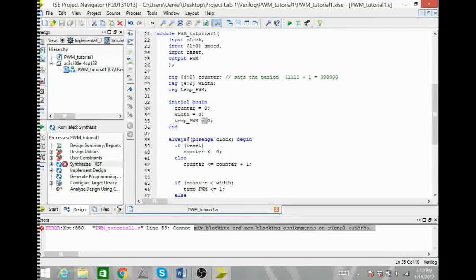So this one would be a blocking. In blocking, it creates a sequential mode where the next line will not be allowed to happen until this first line completes. So that's what the term blocking is called. So it blocks the next line from happening, creating this sequential order. And if all three of these were non-blocking, then they would all happen at the same time and not in a sequential order.